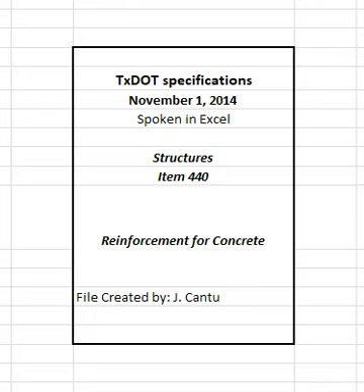For bars exceeding 30 feet in plan length, the distance center to center of splices must be at least 30 feet minus 1 splice length, with no more than one individual bar length less than 10 feet. Make lap splices not shown on the plans, but otherwise permitted, in accordance with Table 6. Maintain the specified concrete cover and spacing at splices, and place the lap spliced bars in contact, securely tied together.